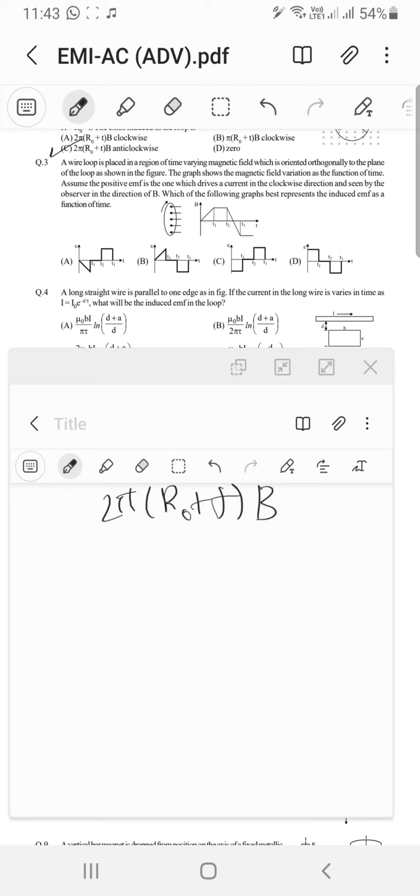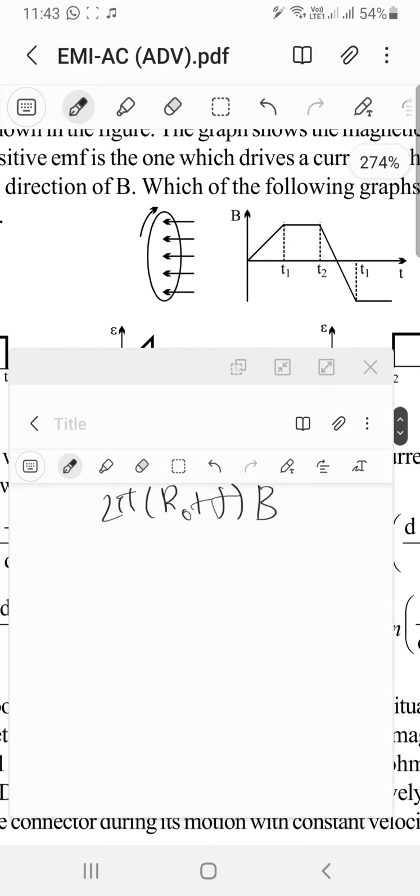Right, fine. So first of all, your magnetic field is increasing steadily, right? So it tries to oppose that. So it should create a field that's in this direction, and for that it has to do this thing, right? Using the right hand rule, it has to do that, which means it's creating a negative EMF in that case.